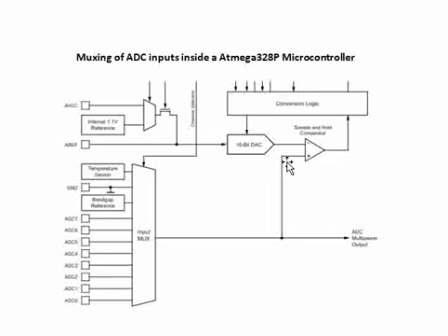You can see here there is a comparator. We have given this Vin to this sample and hold circuit, and then this will be given to the SAR register, where it converts it into a digital value, and the digital value will be given to a DAC, which again gives an output. So again, the successive approximation register.